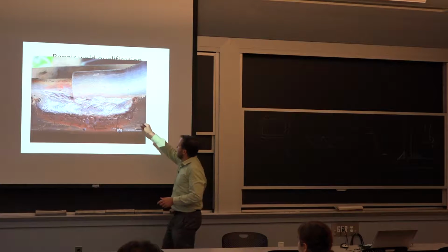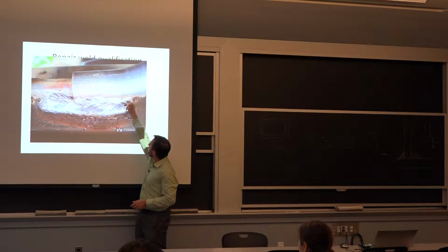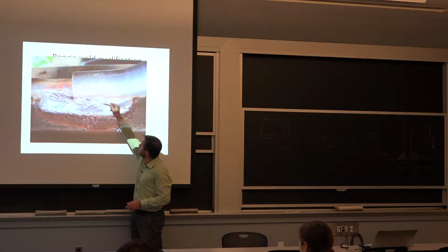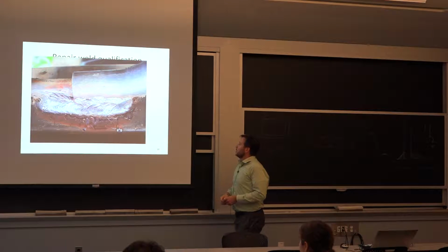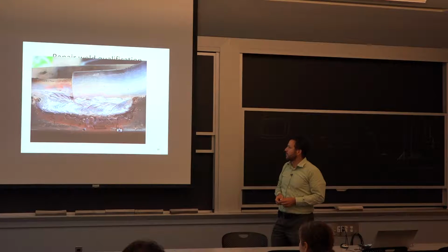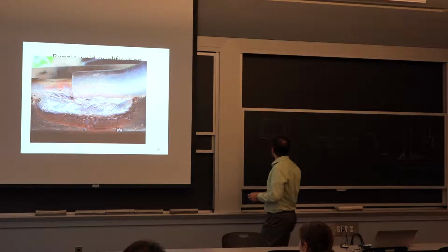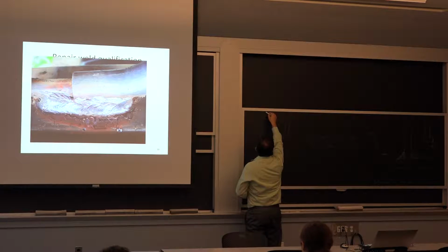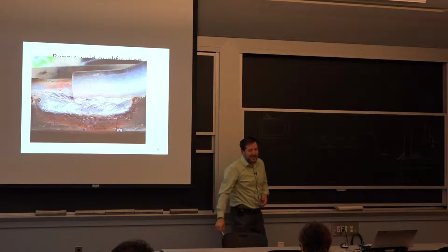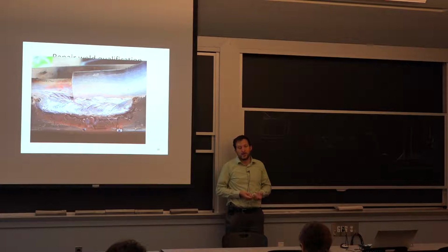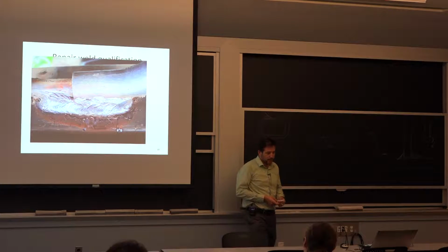You can see that they've put on multiple beads. So over from here to here, it's a different orientation. It's a different pass of welding than down here. And that, of course, will help in terms of filling this entire area, because you have to keep in mind that we have this bar here, and there's just a lot of space, and you can't get all the way to the center. So all you can do is fill that space here. And it's called a flare bevel groove weld. It's not the most common, but it's used in large quantity for cost reasons.